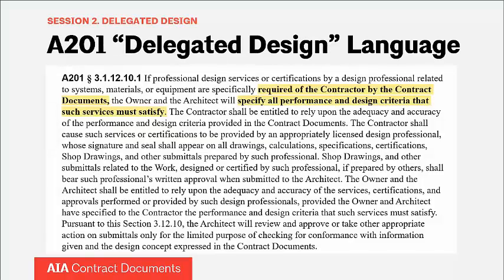Okay, so here I just want to show that the A201 that everyone probably knows does have a process for delegated design already built into it. And it's no surprise that the way we define delegated design in the language that I've already talked about in the paper that we wrote with AISC matches up with the way the A201 works. I'm paraphrasing here, but the A201 sets up a process where the primary design professional can delegate portions of the design through the contract documents that it prepares.